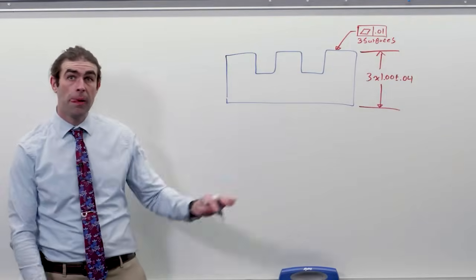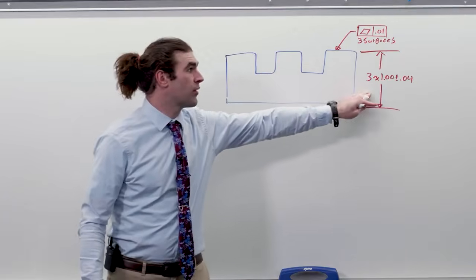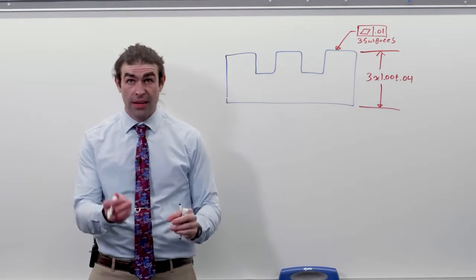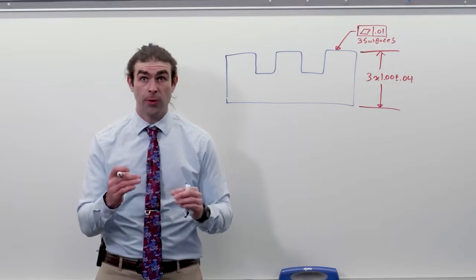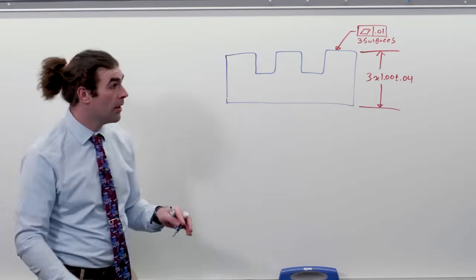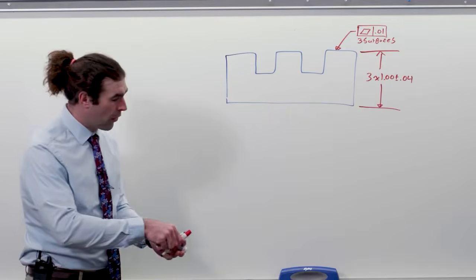Let's look at this. We've got a flatness applied to 3 surfaces, and we've got this dimension that applies in 1, 2, 3 places. That does not control coplanarity, because flatness is an individual requirement. So is parallelism. What you could get with this part are 3 very flat surfaces that have nothing to do with each other.